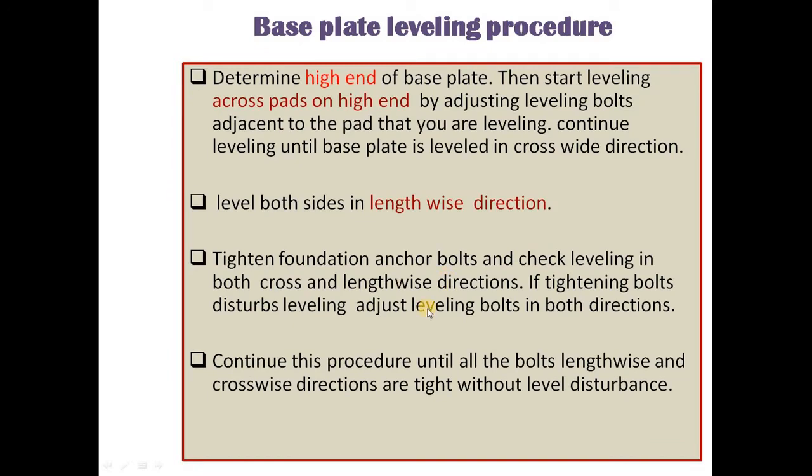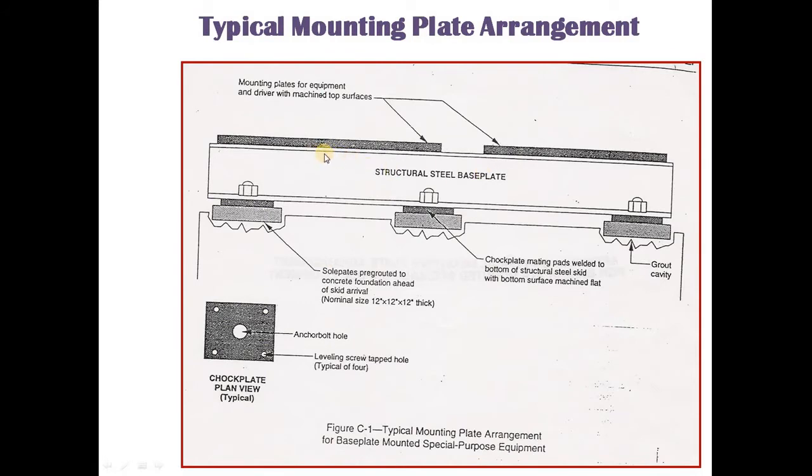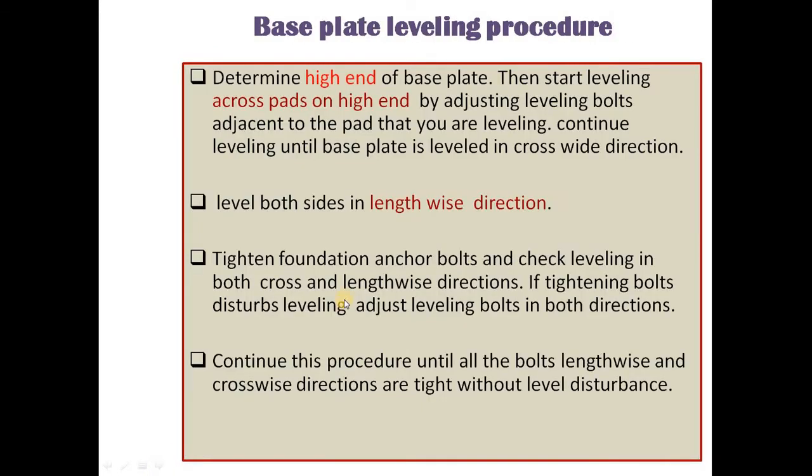Then the base plate leveling procedure. This is called the base plate, over which the mounting plates are there. While doing the base plate leveling, we have to determine the high end of the base plate, because if you choose a low end of the base plate and need to take out some shims to level it, you cannot do that.